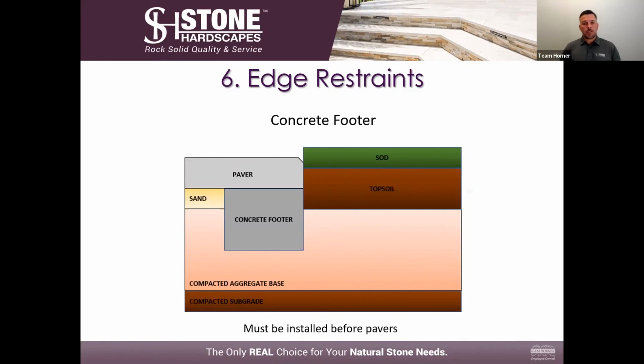The disadvantage to a concrete footer is it has to be done before the pavers are laid, and you have to ensure that you have the proper pitch and elevation, because those pavers are going to run right on top of that footer. So you have to make sure that the top of that footer is exactly where you need it to be on the installation.